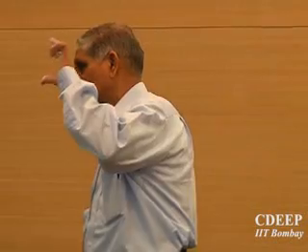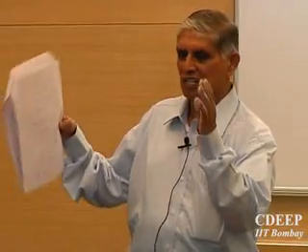W by L is size, W and L. If I increase the size of a transistor, then I can increase gain of any amplifier. Is that correct? So you will see that larger the W by L transistor you put, larger gains you can attain. If I increase IDS, what effect in circuit will I have other than this gm r0 thing?